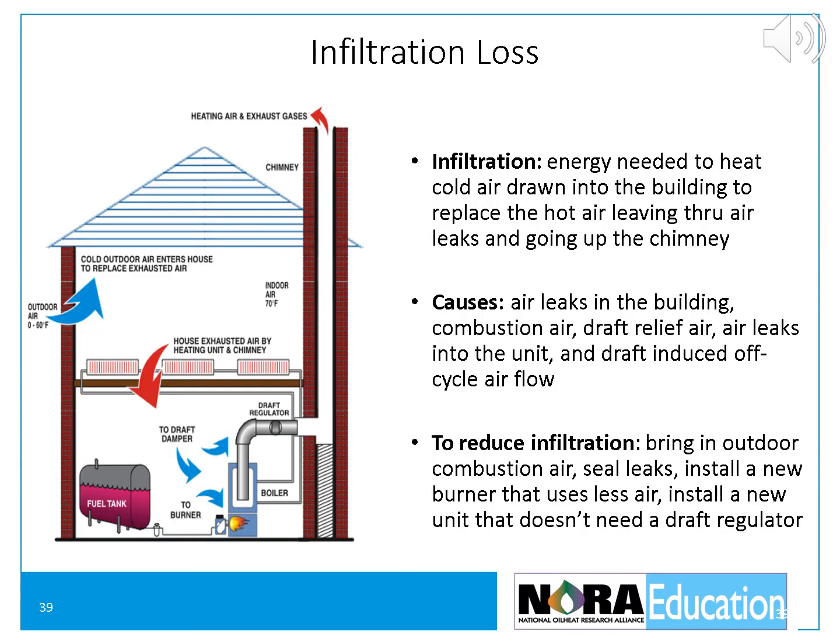Outdoor air infiltration. All fuel burning heating units consume air for combustion and for off-cycle draft. The air that passes out of the building through the chimney must be replaced by cold air drawn into the building. When the cold air is brought into the building, it goes through the living space and is heated. The energy required to heat the cold air is infiltration loss. In most cases, a burner operating in an unconfined space of a conventional building will receive adequate combustion air supply from air leaks into the building.